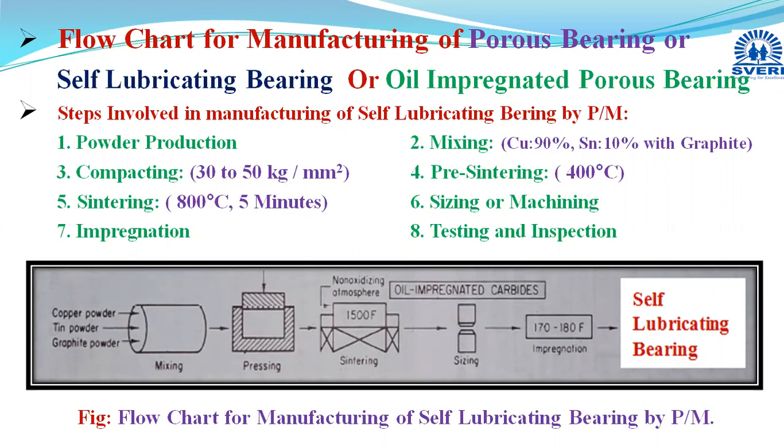Then sometimes, due to proper pressing, some plastic deformation may occur in the powder particles, and these plastically deformed powder particles will help in the sintering stage.